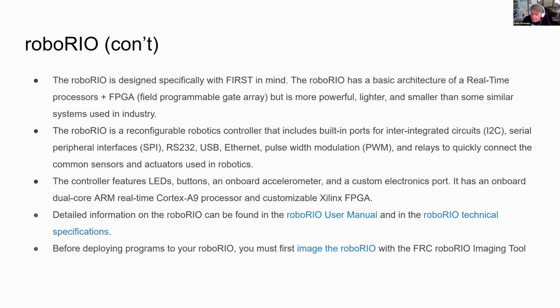You can get gyroscopes, distance sensors, temperature sensors, barometer sensors. Pretty much if they have a sensor for it, you can get it. And so we use I2C when we want to connect to things like the lidars and some of the more advanced distance sensors.